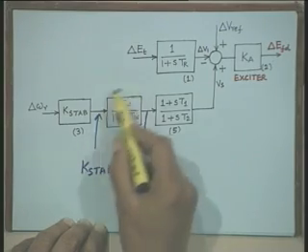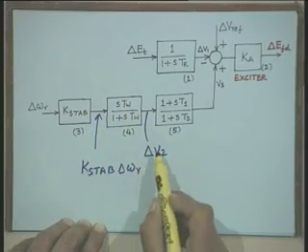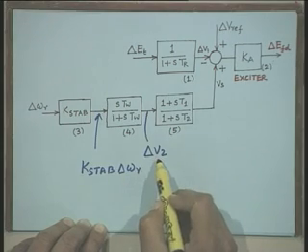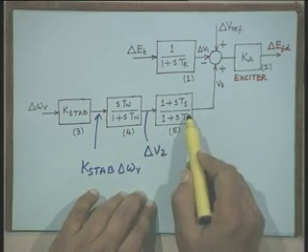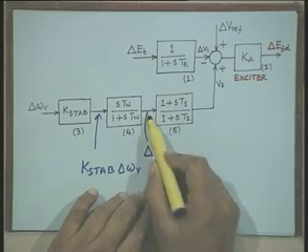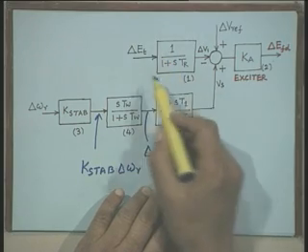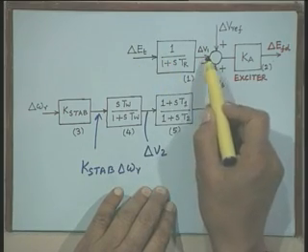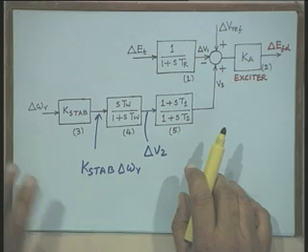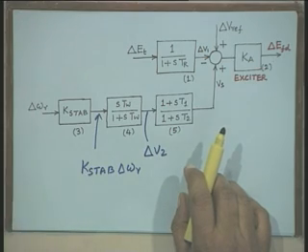okay. So far as this block is concerned, the input is this quantity and the output is delta V2. So far as the second block, or phase compensator, is concerned, the input is delta V2 and the output is Vs. For block 1, the input is delta Et and the output is delta V1. Therefore, these 3 state variables are required to develop the complete model of the machine infinite bus system, including PSS and AVR, right. Now, the equations can be written very easily.